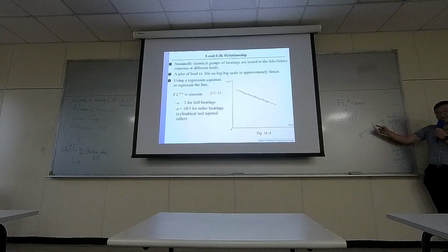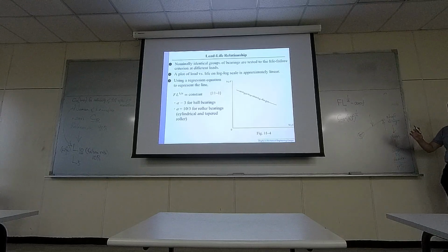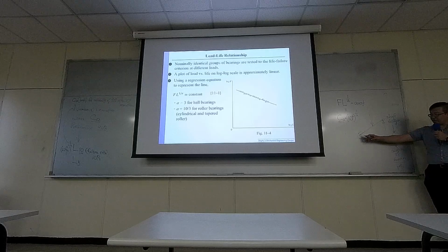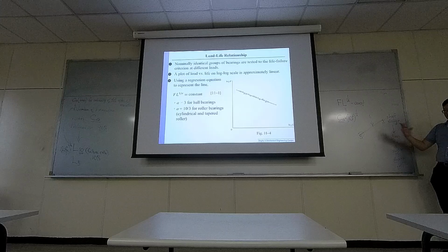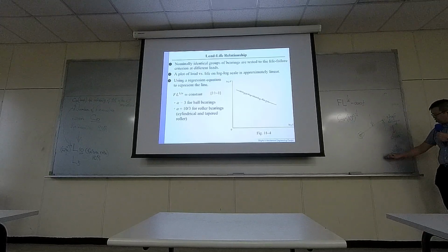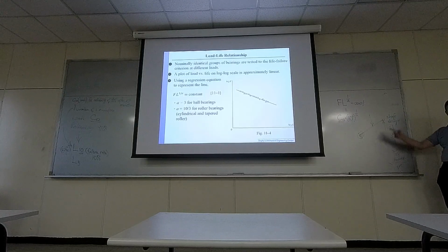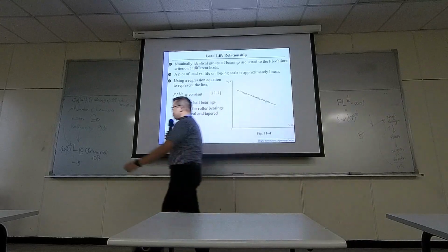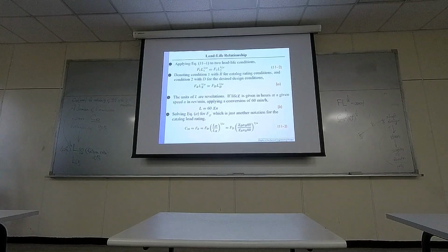Dimensions means you decide the dimension of the shaft and some other things, so that you realize the shaft is strong enough. And then you decide the parts that are assembled together with the shaft. Once you have that, you may want to go back and check if everything matches your initial design. Sometimes you need to do this iteratively so that everything converges. So this is exactly what I mean.